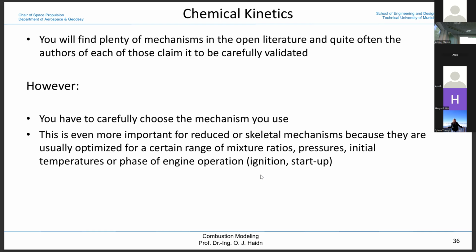People try to determine locally the time scale of the chemical reaction and relate it to the time scale of the flow. From a computational point of view, you have a residence time of the mixture inside the computational cell. The residence time is smaller than the time to reach the chemical equilibrium. So you cannot assume that you have a chemical equilibrium, meaning the classical flamelet approach is not working.